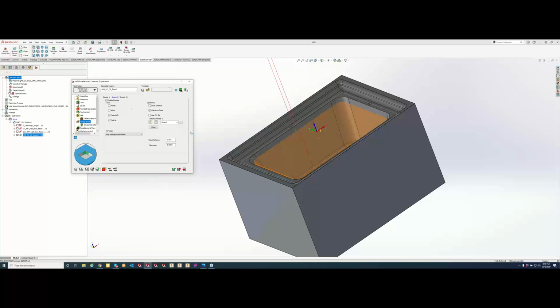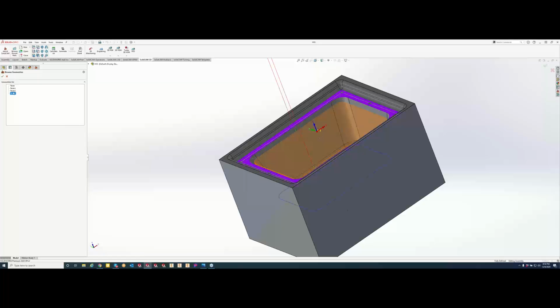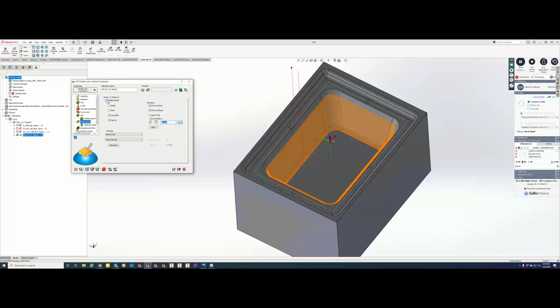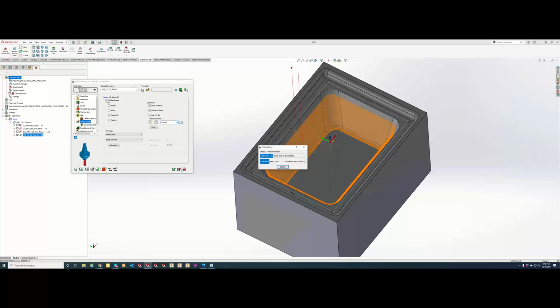Now, if we're just doing off the same one, definitely you can do it all within gouge 1. I don't remember which one mine was, so I can just hit this little browse button right here and find, yep, that's the one, because it's covering the top and the bottom. We can do it in that case right there. So when your strategy is the same for your check surface as well as your drive surface, you can definitely keep them all in one. Just remember that you will not be able to do the stock leave option on your check surfaces. So does that help out, Duncan?